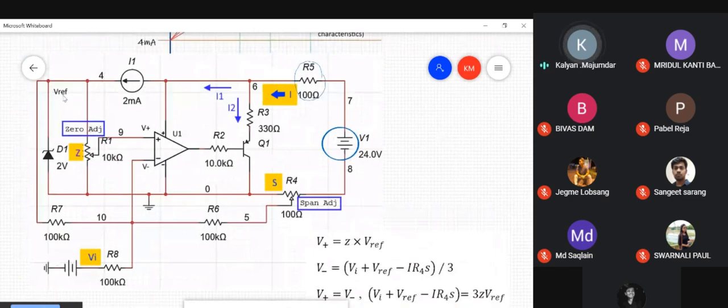See, it's V reference, means it's a reference voltage, means it's a voltage which is constant, irrespective of supply voltage variations at this particular point, because if the supply voltage changes, this voltage will change, but you want the voltage across this particular Zener diode to remain constant, strictly constant against supply voltage variations, against temperature variations. So what you do is you bias this particular Zener diode using a constant current source. Of course, the constant current source has got to be electronically implemented, but you can use a resistance, but constant current source biasing of a Zener is a far better option. Why, I am sure you know this, but still just making a sketch of it.